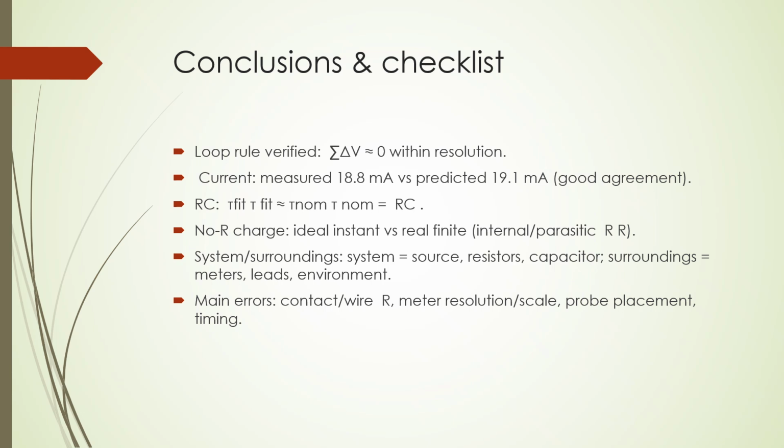Main errors could be contact/wire R, meter resolution, scale, probe placement, and timing.